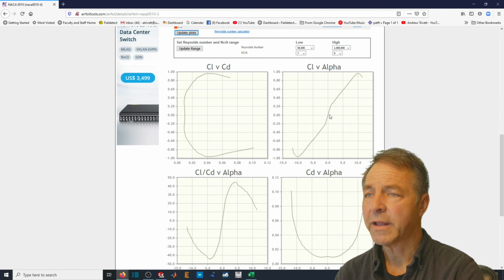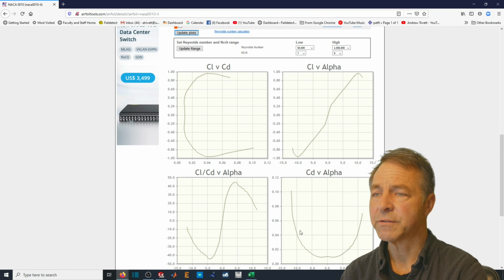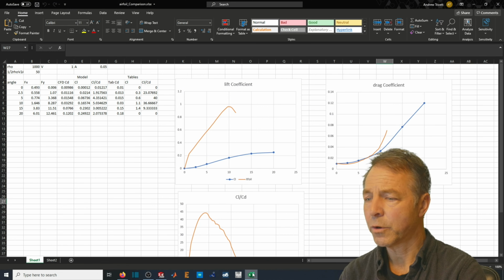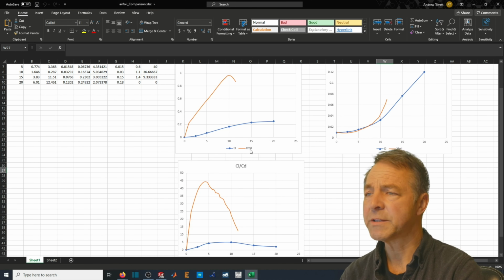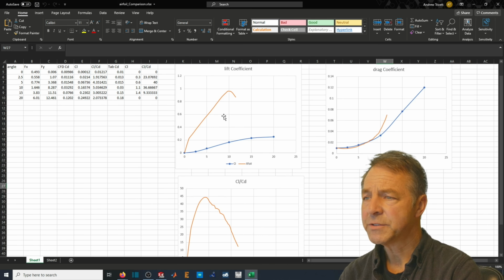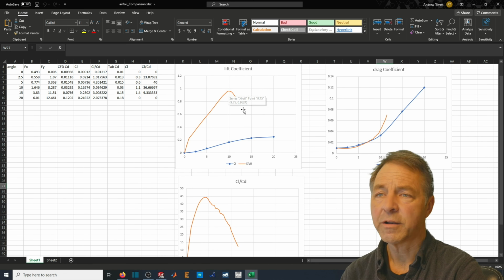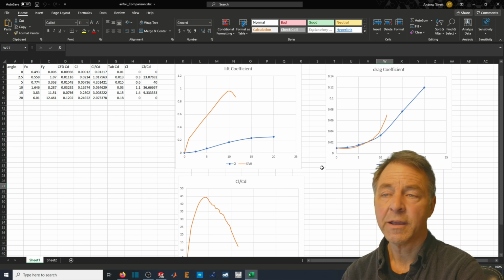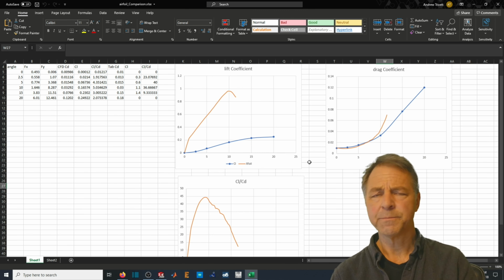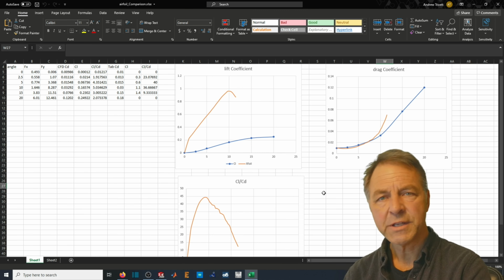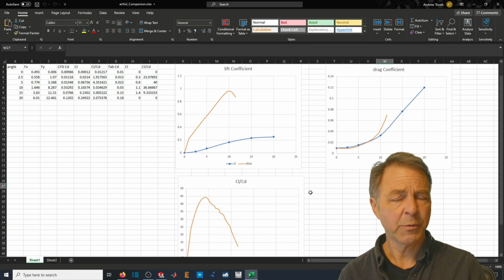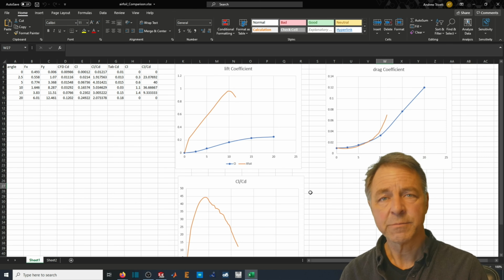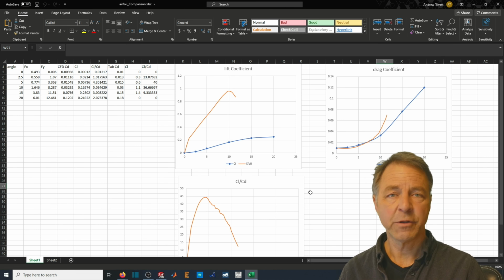If I compare that to these graphs of lift and drag, or to my own lift and drag data, my own plots, at 10 degrees, I should be seeing a lot of lift as compared to the drag. And that simulation showed something different. And you could see from the way it was not converging that there was something going on. Now, this is the real challenge with flow simulations.